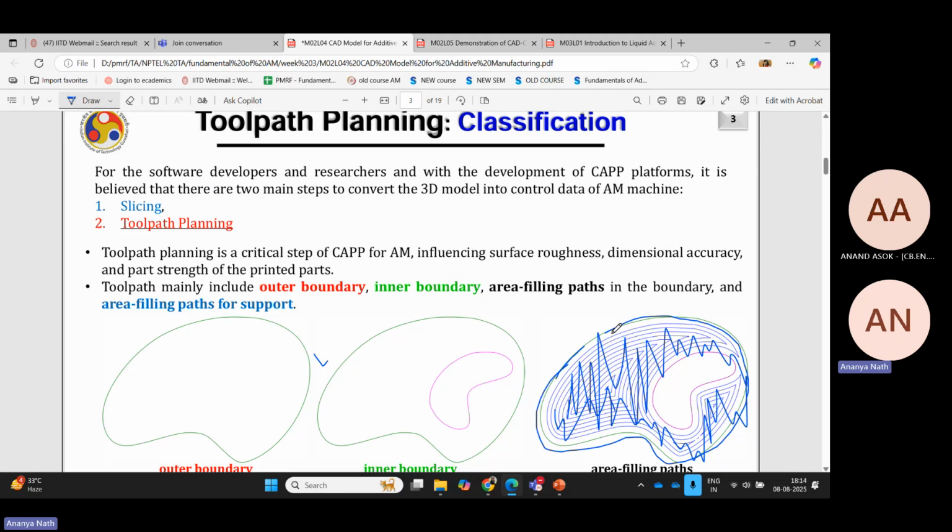So to avoid the surface roughness and porosity due to this, the laser will rescan the periphery to remelt it and make it more defined, as a result of which the unfused powder particles will be remelted and fused together, and the porosity and surface roughness will decrease. So this is the reason for contour scanning in LPBF.